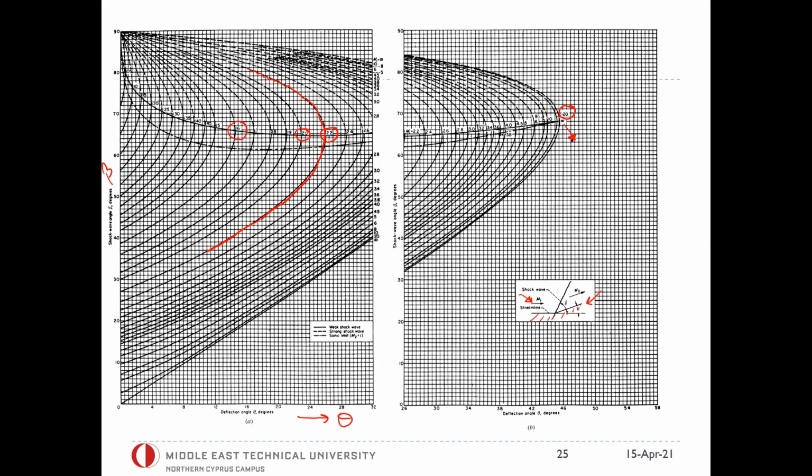So this one, if you remember, actually corresponds to a certain theta max angle theoretically. It's down here, 45.5 degrees, we said yesterday. So depending on your free stream Mach number, and if you know your theta deflection, using this chart you can directly find the beta value of the oblique shock wave that is going to form at the corner of the deflection point.